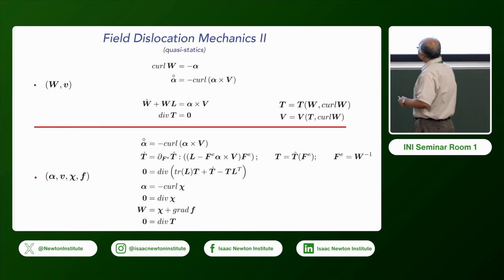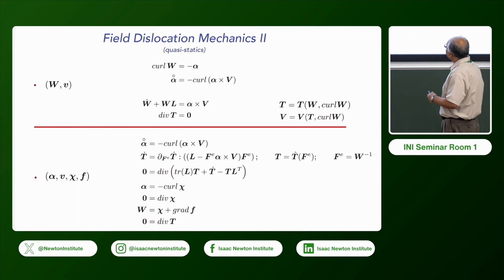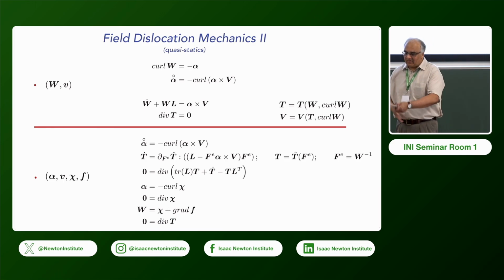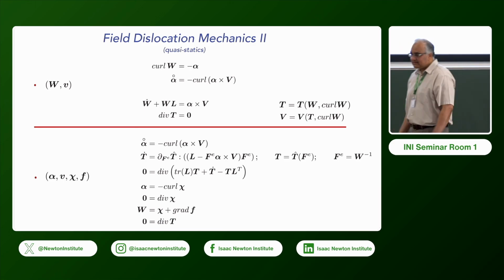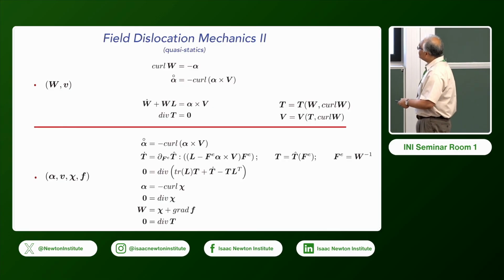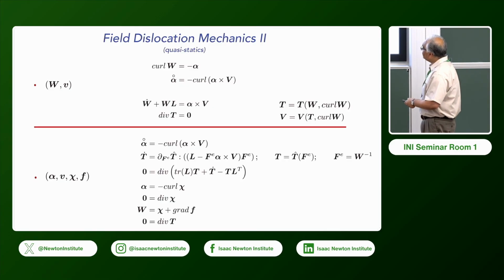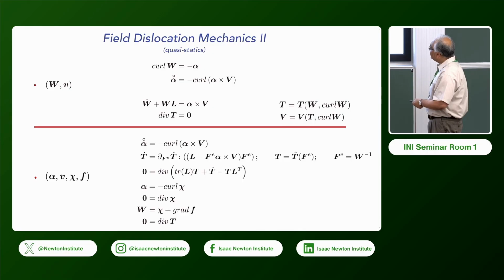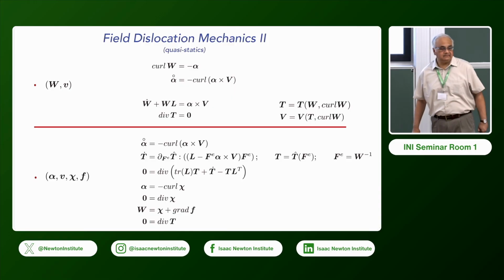And then instead of solving that equation, you solve this equation, which still has a conservation form, so you can at least move one set of derivatives onto test functions, etc. And the way you solve the stress problem is, suppose you're given this, then you solve for the incompatible part, stick that into the W, go into there and solve for the F.